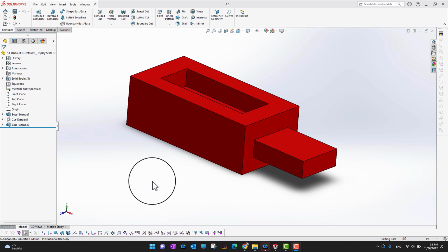If you are working on a part designed for a molding process like plastic injection molding or die casting, you need to apply draft on your part. That way, later on, when you want to separate the mold and the part from each other, it can come out very easily. Draft is a specific angle on some faces which you can apply by using SolidWorks.